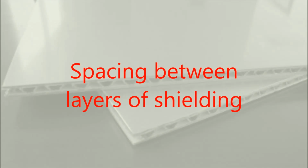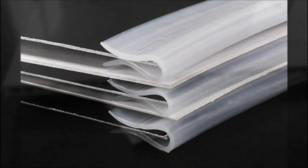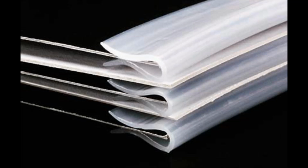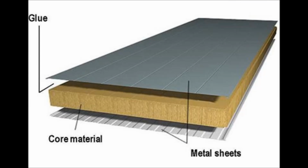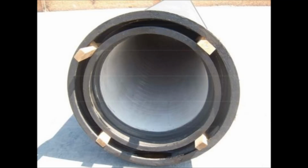Spacing between layers of shielding. Spacing between layers of shielding increases shield performance. The larger the space, the better the performance. Almost any material can be used as a spacer: wood, plastic, drywall, glass, air, cardboard, other metals, etc. Other considerations such as cost, strength, flammability, weight, etc. must be taken into account.